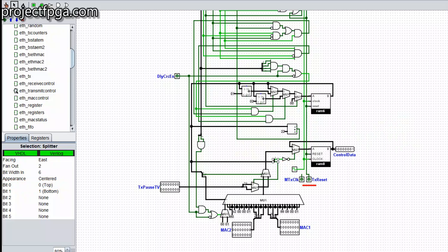The major reason for that is so that when we are transmitting, we send nibble by nibble. The nibble will be able to send 4 bits at a time. Then while it's off, it's going to send the remaining 4 bits. So that is the reason why this multiplexer updates this control data. One clock cycle it skips one, another clock cycle it skips one.